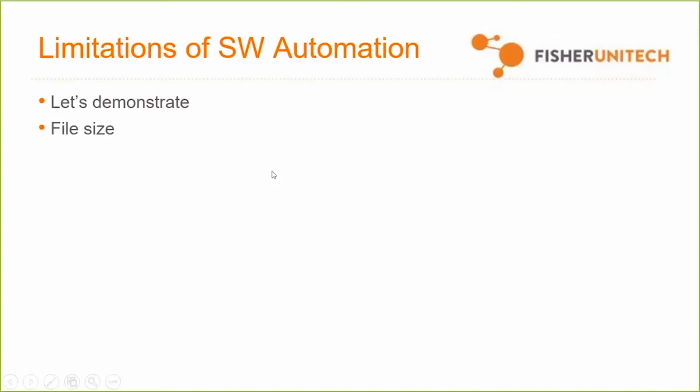One, if you have lots of configurations when you're dealing with SolidWorks automation and you're trying to make a lot of configurations quickly, that's going to blow up your file size, and it might lead to some slowness, or it just might be inconvenient that it's so large. The one that we just saw, obviously, was slowness of the file itself, because if you have lots of equations going on, those equations require a certain amount of processing power in order to get their job done, and that processing power is definitely going to cause some slowness in some cases.